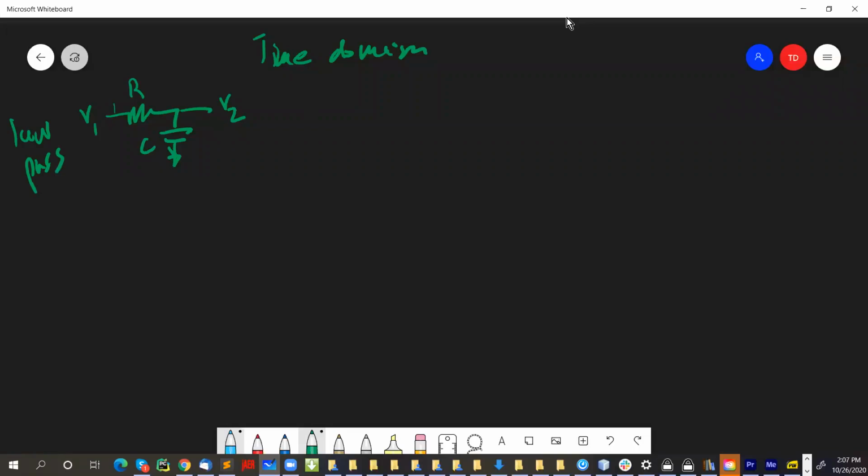And in fact, the frequency domain response of this thing, you can almost guess what it looks like if I have frequency on this axis and a log scale, and I put the log of the gain, the log of the magnitude of V2 over V1, which is also called H. I don't know why they call it H, but anyway, the magnitude of V2 over V1 is usually called H. It's a function called H of F or omega.